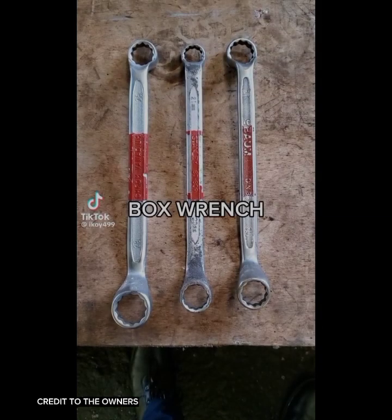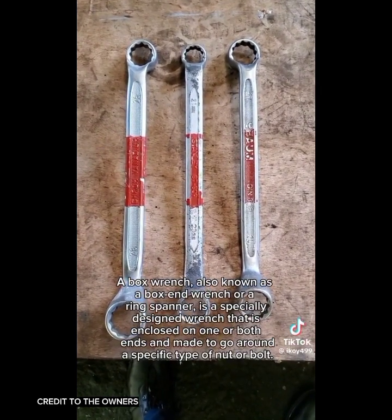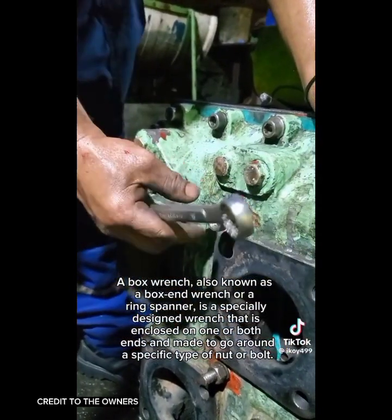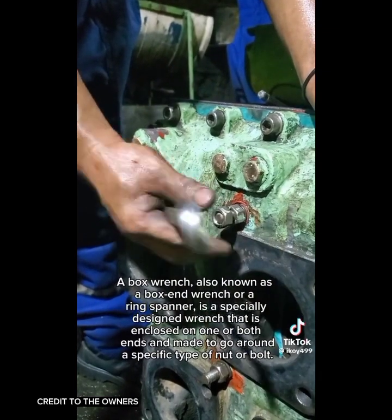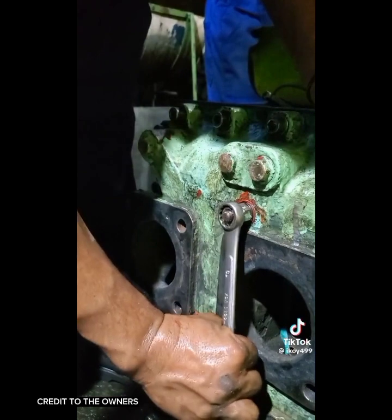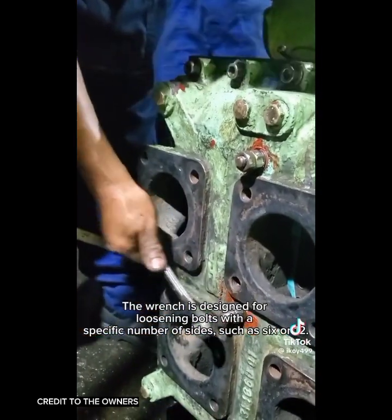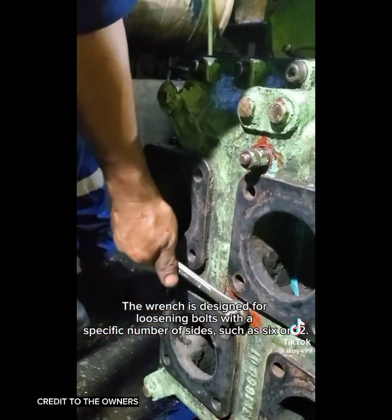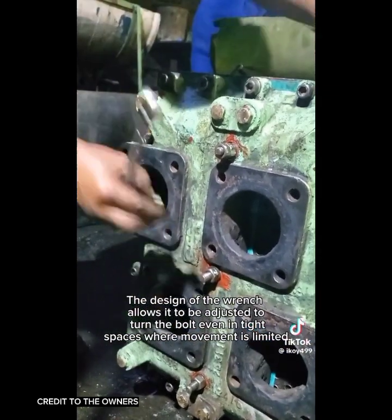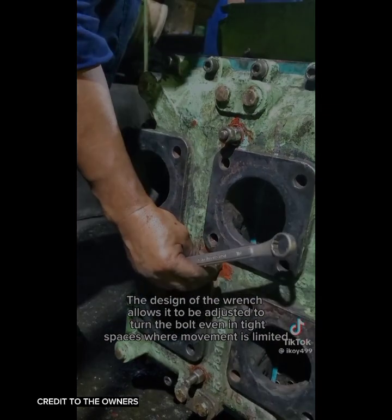Box wrench. A box wrench, also known as a box end wrench or a ring spanner, is a specially designed wrench that is enclosed on one or both ends and made to go round a specific type of nut or bolt. The wrench is designed for loosening bolts with a specific number of sides, such as 6 or 12. The design of the wrench allows it to be adjusted to turn the bolt even in tight spaces where movement is limited.